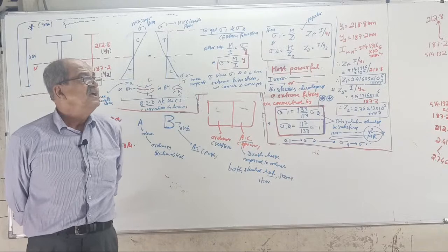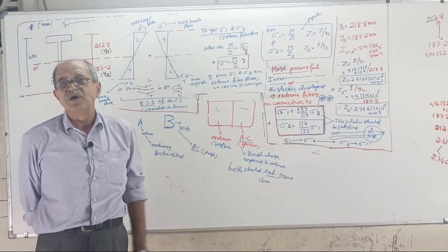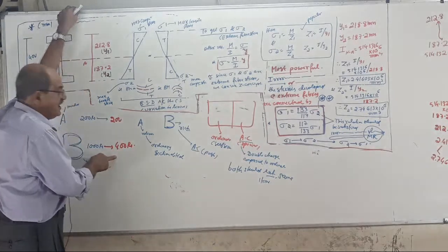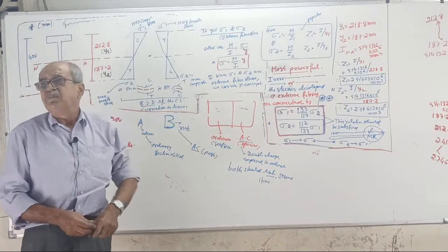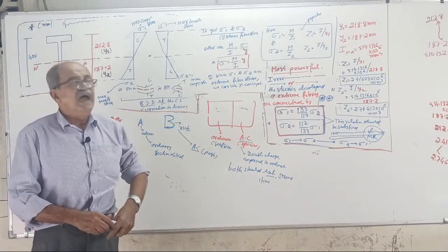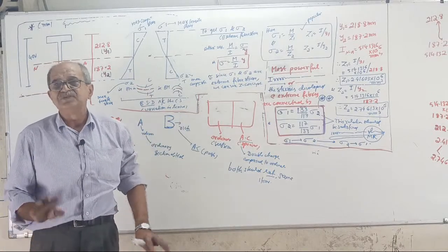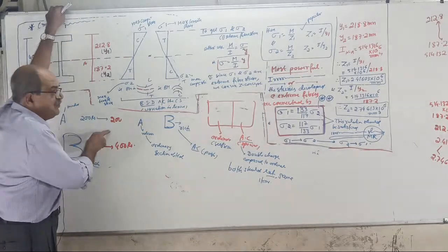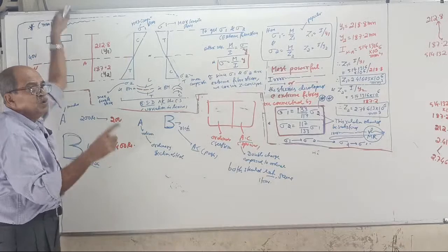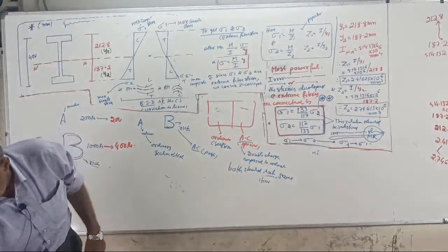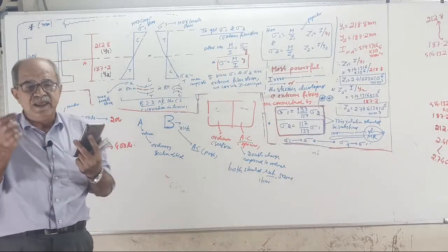Over-reinforced section means steel is provided in excess than required. Now clear? In RCC, when steel is provided where it cannot be fully stressed, or the area of steel available is more than that required for the balanced section, it is called over-reinforced section. If you connect it to RCC, this is like over-reinforced section. Clear now? It is equivalent to over-reinforced section.